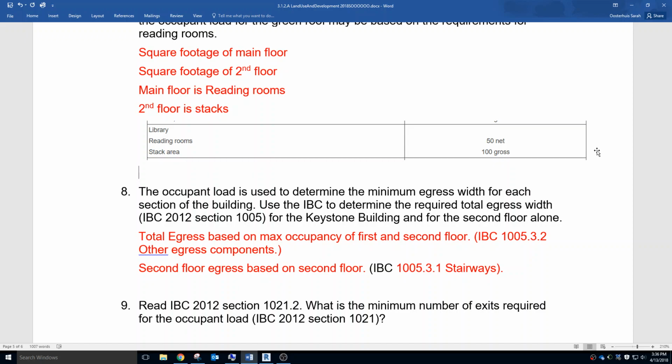You're going to say, let's say for the first floor, if your area was, let's say, around 8,640 square feet, then that divided by, let's put this in parentheses, 50 square feet per occupant is going to equal around 172 occupants for that number of square feet.